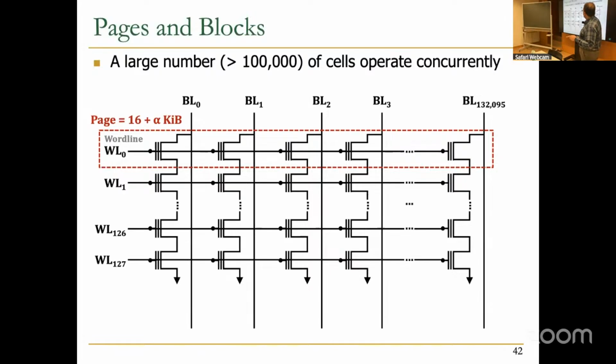Okay. So actually, as an interesting alternative, we also have NOR flash. This is NAND flash, but we also have NOR flash, where the string is a bit different. You have more connectivity, and that provides you better performance and less latency, but then your density is lower and the cost is higher. So that's why today's SSDs, because they want good capacity and good density, are using NAND flash memory. But when you care a lot about the performance, you might use NOR flash memory as well.